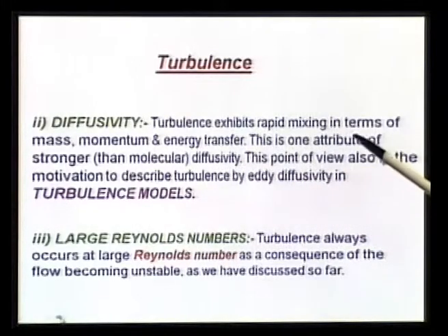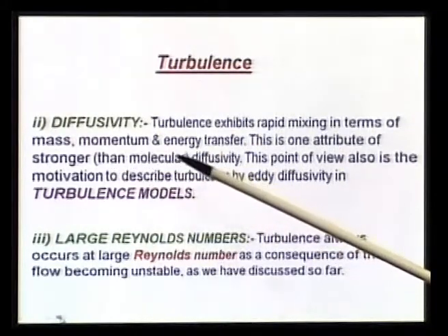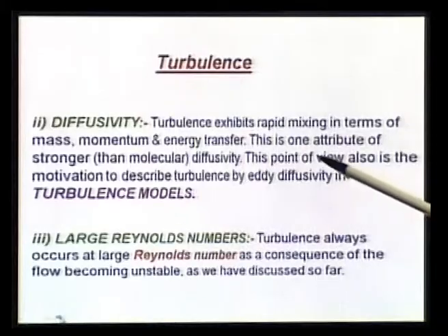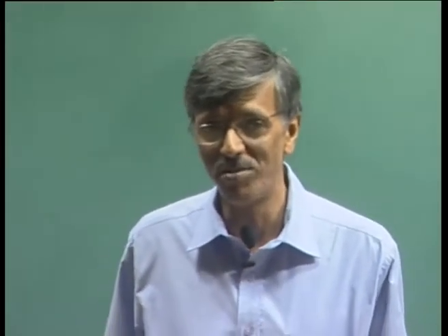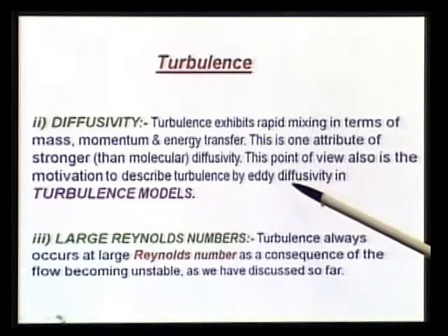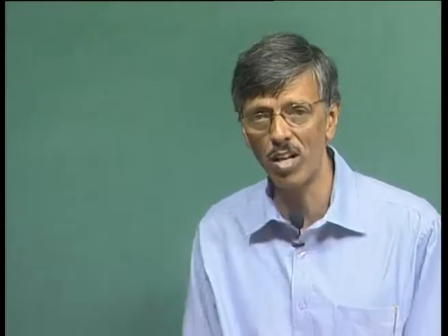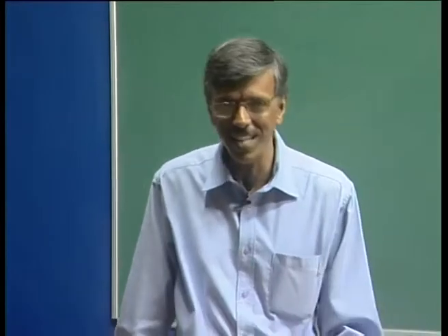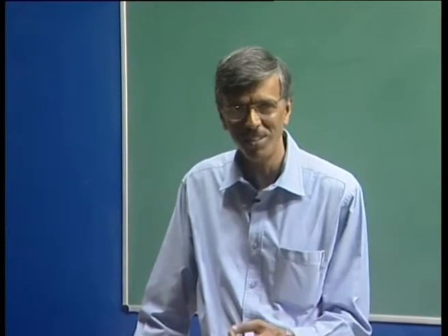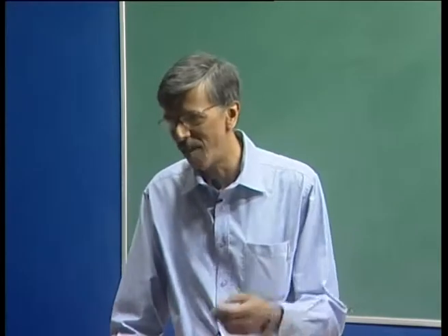So, that is what we are saying, that this is one attribute which is much stronger than your molecular diffusivity. This is something very, very important. And unfortunately, this point of view also is the motivation to describe turbulence in terms of a diffusivity coefficient. That is what goes by the name of eddy diffusivity, that is modeled most of the time in turbulence models. But please do not try to understand, in the name of engineering fluid mechanics, turbulence in terms of coefficients of turbulence models. That is far from the truth.